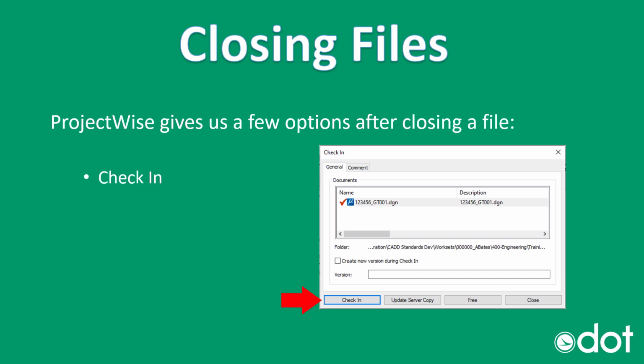And what this button does is it uploads any document changes to the ProjectWise servers. So anything that you've copied out, any of the design files you made changes, those changes are being made to your local copy outside of ProjectWise and are available in your working directory. These show up to everyone else that has this as this red check mark here, as you can see within the dialog. So once you've hit check in, those changes will be seen by other users to modify that file.